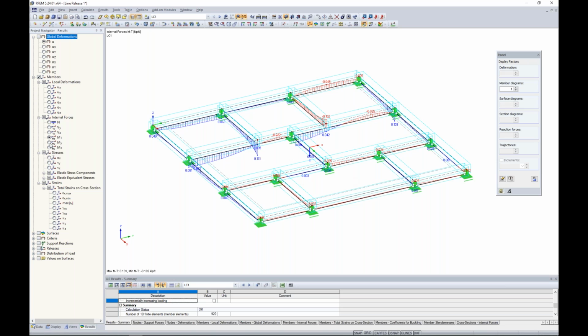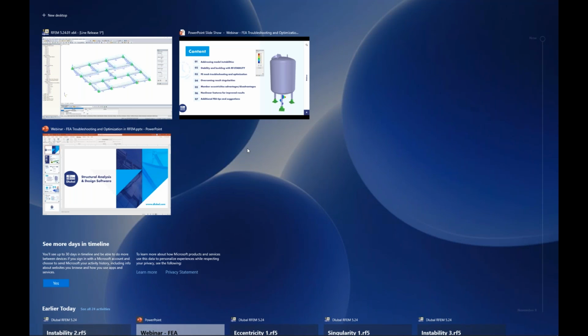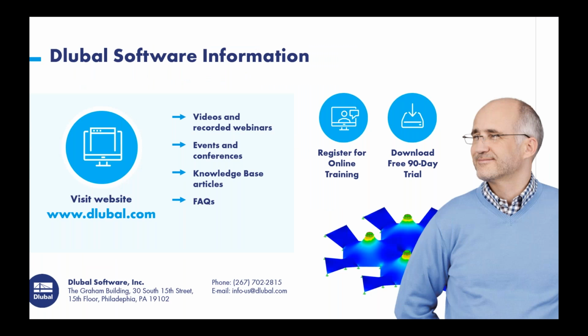If we take a look at our strong axis bending, we're no longer seeing those high peak negative bending forces either, which is exactly as you'd expect here. We have positive bending for all of our member elements. So some of these nonlinear applications can further be used in the program to really get the desired behavior that we want.